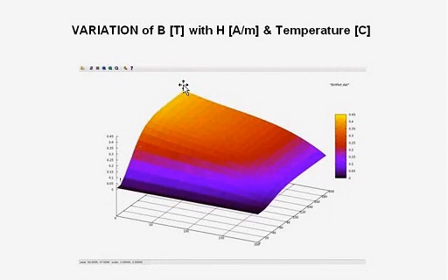I had the BH curve using the hyperbolic tangent in this direction, and then I multiplied that by the replica of the Curie-Weiss curve, which is not quite true for a complex material like a ferrite, where they actually tailor the crystalline structure to modify the Curie-Weiss curve. But that was the best I could do in the time I had, and it's fairly close to the real properties as far as I could see.